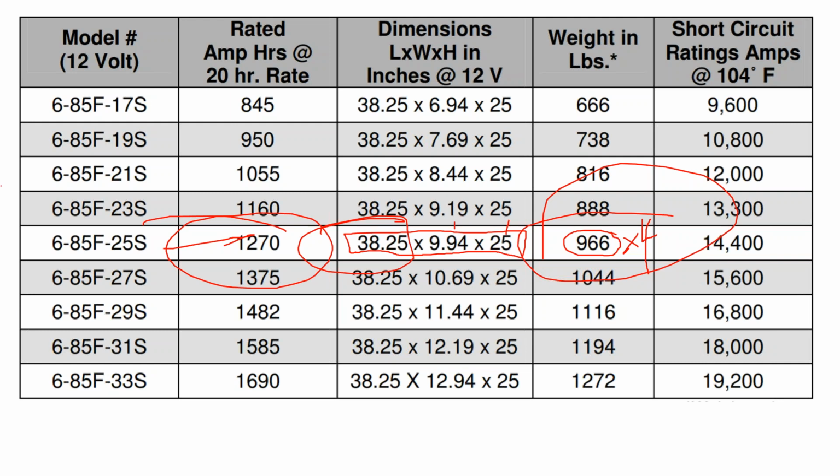What's nice about going with these industrial forklift batteries is that they're tall, so they have the most density, in the sense that instead of having 48 batteries that you have to wire up, you only have 8 batteries. And instead of wiring up 48 batteries and then building a case and shelving system, the 8 batteries come with the case kind of integrated into it. So you get a more professional, complete battery when you go for the industrial forklift batteries.